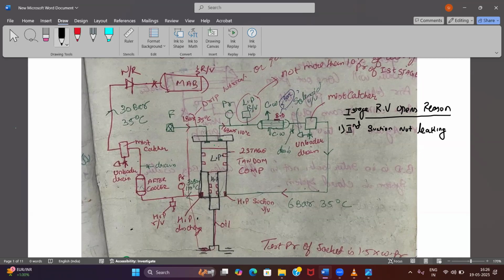That is leaking. Then when the high pressure piston is going down and compressing, this pressure will be gone from here instead of the discharge valve. If it is leaking, it will leak out from here. Agree? Yes, sir.